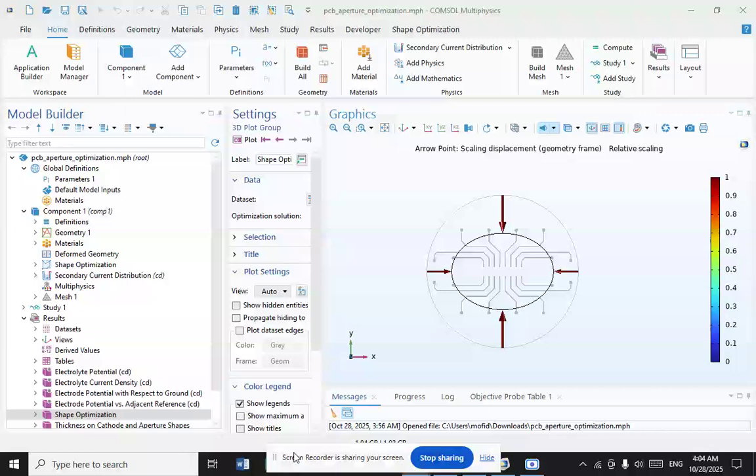It is used to build up thickness on undersized or worn out parts and to manufacture metal plates with complex shape, a process called electroforming. It is used to deposit copper and other conductors in forming printed circuit boards and copper interconnects in integrated circuits. It is also used to purify metals such as copper.